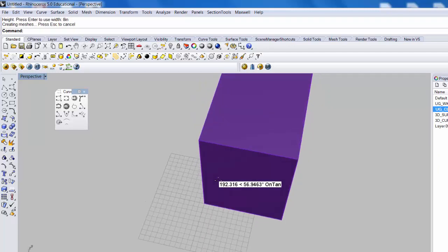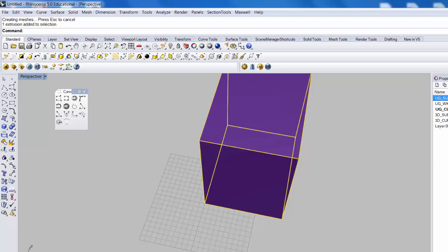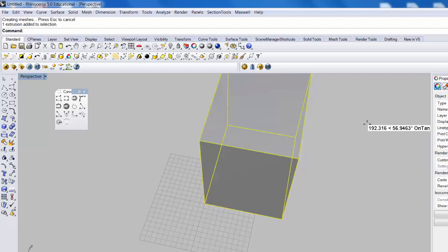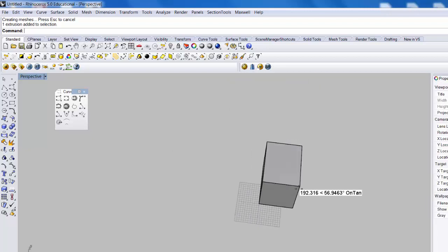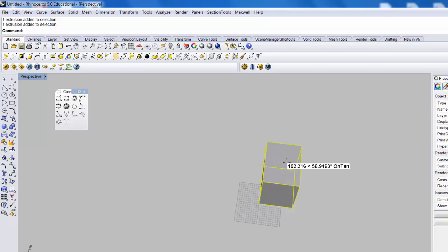So that's my box. And I'm going to put that on another layer, UG, underlying geometry, surface. And to change that layer, I just go to properties and toggle that guy there. Now I also, just conceptually, I like to build things as they're going into the printer. So our printer actually, you go in the short way, so I'm just going to rotate this.